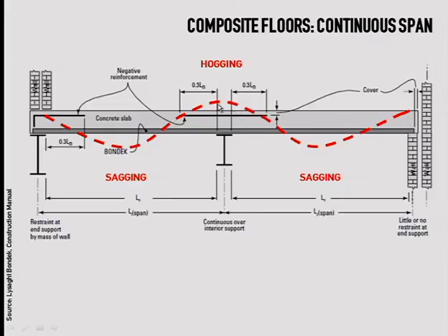So the type of deformation you get is a little bit like this red line that I was drafting on this line. So the reason for these steel bars in the upper parts here and there is because the sign of moment changes. So it goes from positive to negative because you're changing the constraints of the system, right?